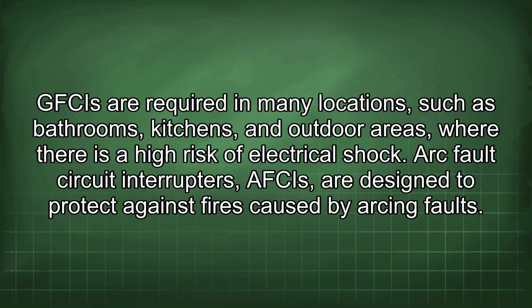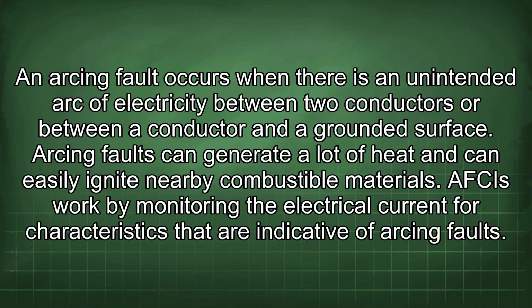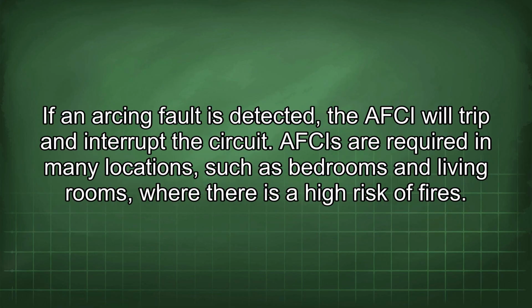GFCIs are required in many locations, such as bathrooms, kitchens, and outdoor areas, where there is a high risk of electrical shock. Arc fault circuit interrupters (AFCIs) are designed to protect against fires caused by arcing faults. An arcing fault occurs when there is an unintended arc of electricity between two conductors or between a conductor and a grounded surface. Arcing faults can generate a lot of heat and can easily ignite nearby combustible materials. AFCIs work by monitoring the electrical current for characteristics that are indicative of arcing faults. If an arcing fault is detected, the AFCI will trip and interrupt the circuit. AFCIs are required in many locations, such as bedrooms and living rooms, where there is a high risk of fires.